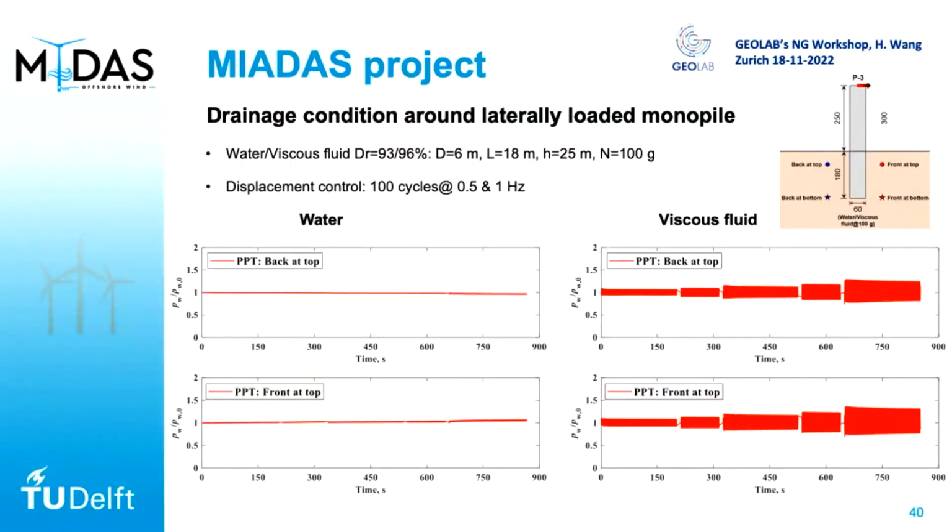But an interesting thing, compared to what we observed in the seismic test, where you observe quite a large excess pore pressure at the beginning that then dissipates, here you really observe a very transient oscillating pore pressure. There is no accumulation. So there is some partially drained response, but it basically means the response is mainly controlled by the drained behavior.